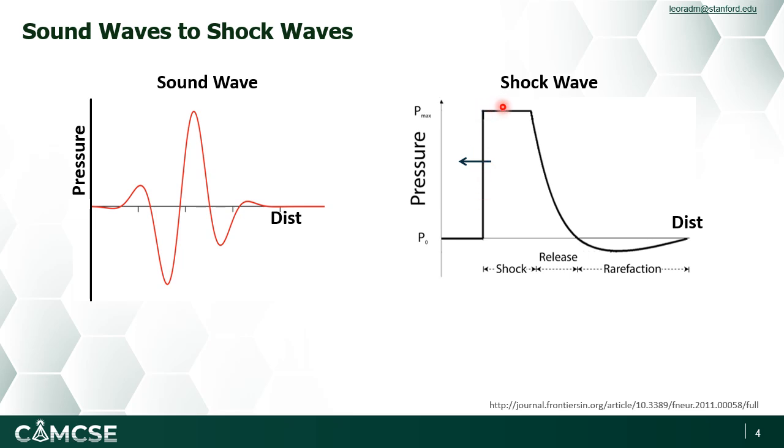Then all of the highest amplitude pieces are together, defining what is called the stable region of a shock wave, or stable compression state. And then following that, we get release and subsequently rarefaction to negative pressure, before eventually we subside to our ambient conditions.